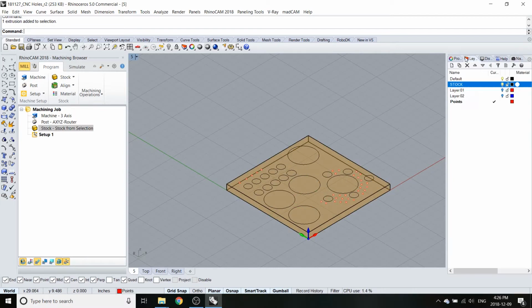Now that the stock has been set up, we can then begin assigning the milling operations. There are two types of hole conditions in this example that will use 2-axis milling operations and the holes milling operations. The holes milling operation can be set up as a series of points along the stock, if the tool bit is coordinated to be the intended diameter. In the cases where the diameter of the holes are slightly larger than the tool bit that is being used, then the 2-axis milling operation can be used instead.